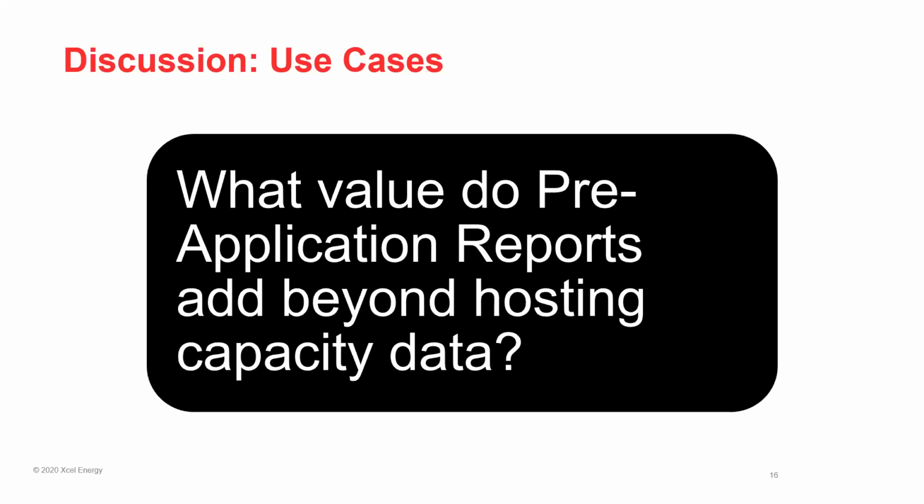Yeah, I mean, that could be some possibility there. The hosting capacity analysis is taking into account what those changes are to the system, at least with the last update, but it isn't necessarily going to tell you that 3 years from now there's a plan on this feeder to upgrade the conductor or whatever it is. There is some of that information available in our integrated distribution plan. So there is that potential, but plans change. It's a pretty dynamic budget, but it could potentially help there as well, just give a little more insight.